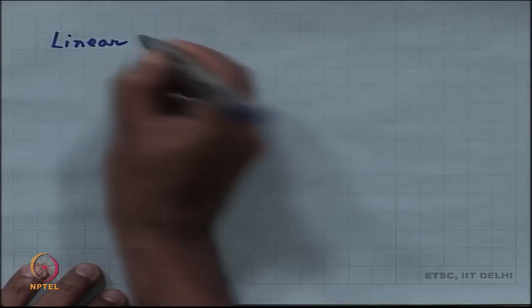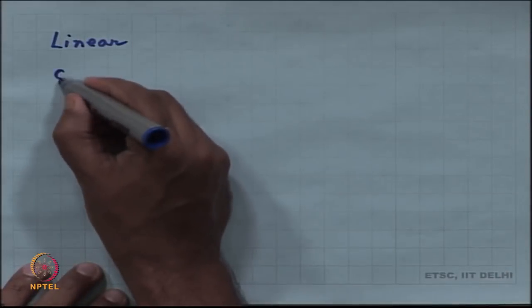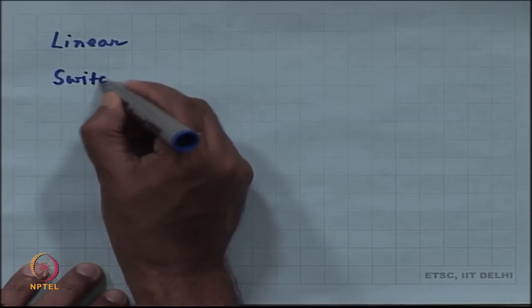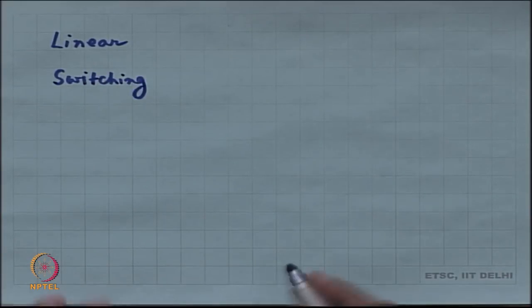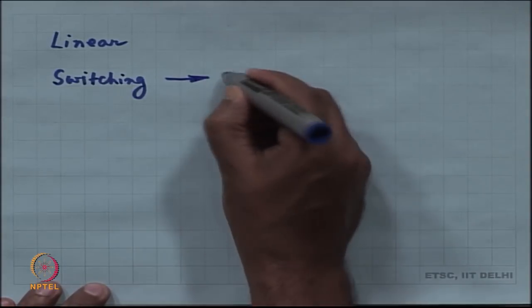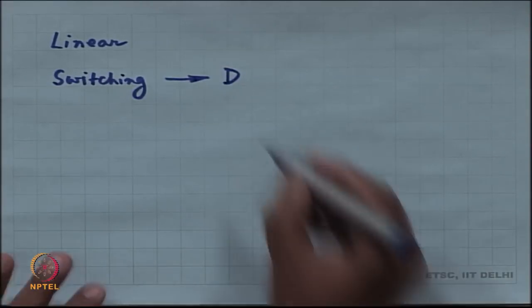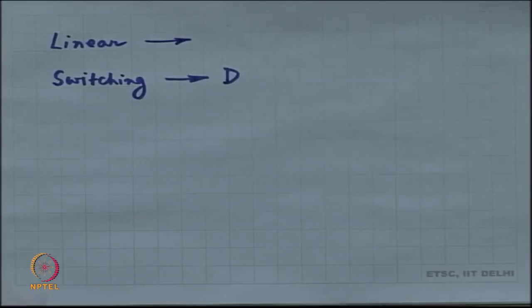All right. So, these power amplifiers can be classified into two broad classes. One class is the linear power amplifier, the other class is the switching power amplifier, okay, where the device is being used as a switch. So, the switching power amplifier is class D, the linear power amplifier, okay, this linear, take it with a pinch of salt, all right. The circuit is not a linear circuit as such.